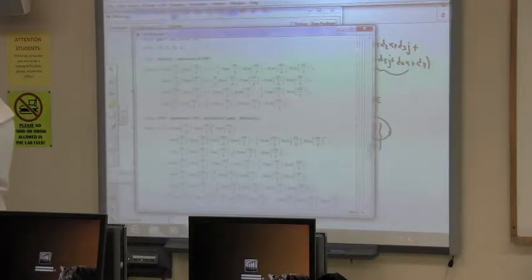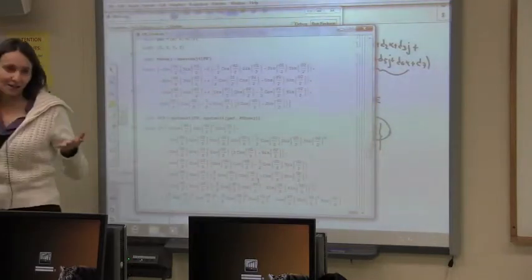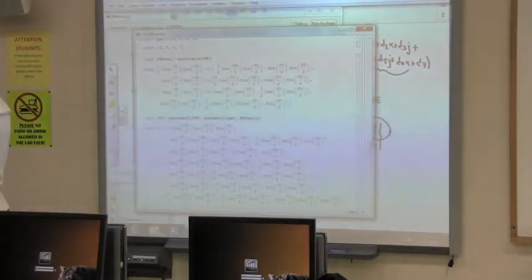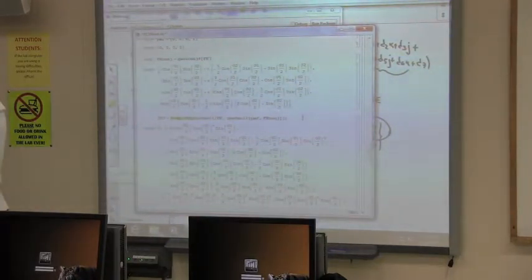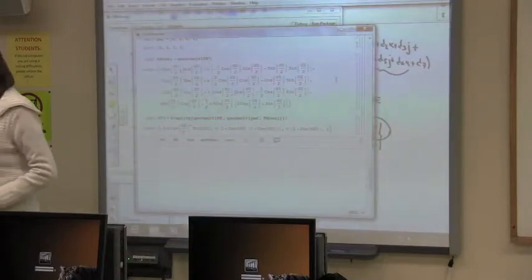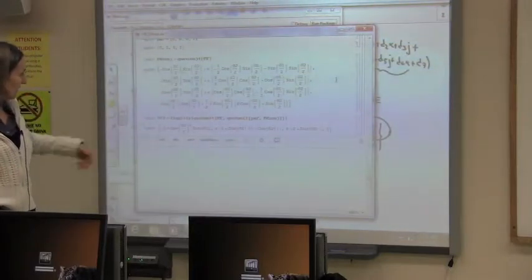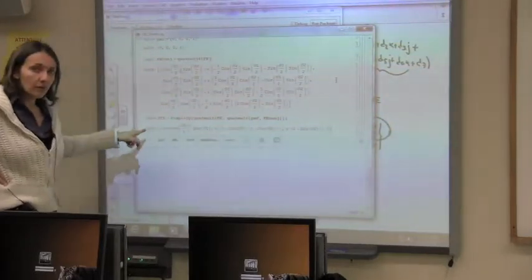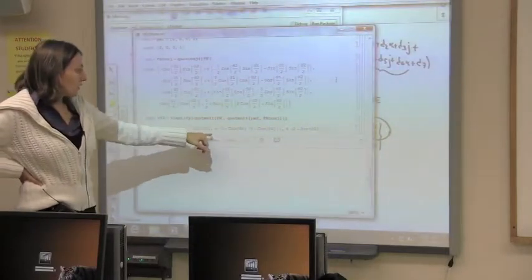Now this could be a little bit long, okay, because it's not simplifying, and Mathematica, Maple and all those are, well, these are programs that are well known for not simplifying as they should. We can put a simplify command in front. See what happens. But it doesn't matter because look at that. You see, could have done that from the beginning, right? All right, so this is the set. This is 1, 2, 3 components. This is a set of all possible locations of the origin of the end effector frame if you give values to theta 1 and theta 2.